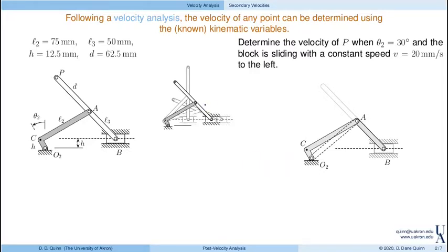and I actually have three different pictures of it. But let me look at this middle picture here. So essentially this mechanism has kind of an L-shaped bracket. We'll call that essentially link 2. That's connected to link 3 and then a slider. So as this slider moves to the left, essentially link 3 rotates up and unfolds. So this might be a mechanism used for a display system that closes and opens, something like that.